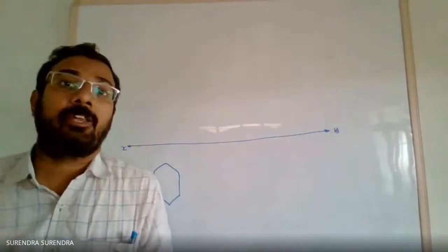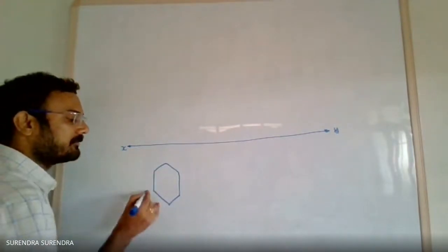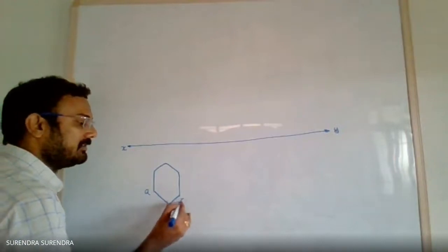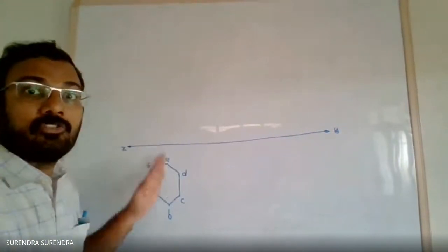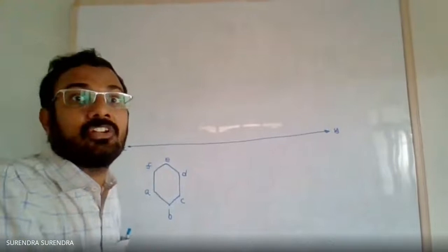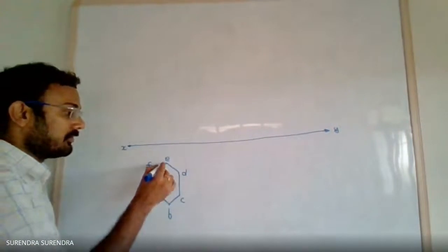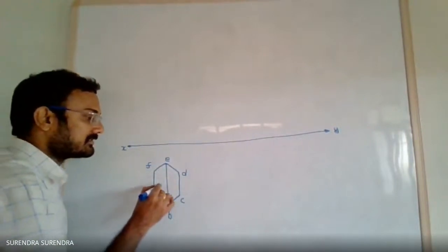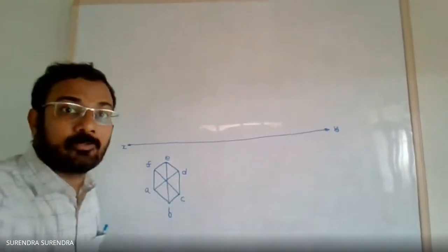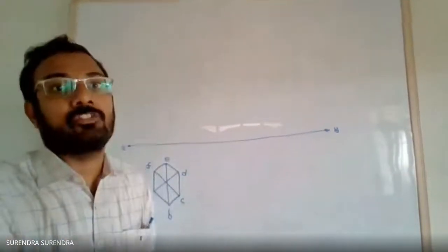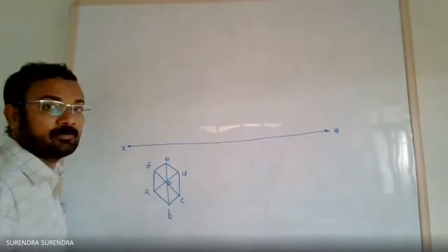Now, as it is a pyramid having only one base, let the base corners be A, B, C, D, E, F. For a pyramid, you have to draw all these lines joining towards the apex. So draw the diagonal lines. For a hexagonal pyramid, when you are seeing from top, you can see all the six triangular faces. This is the point O, the apex point.